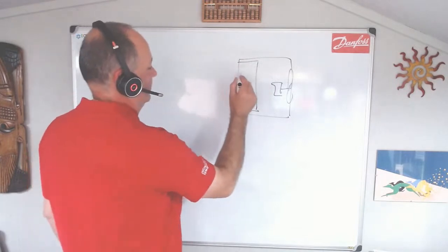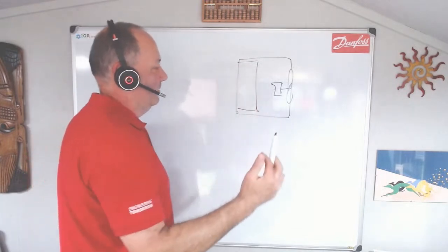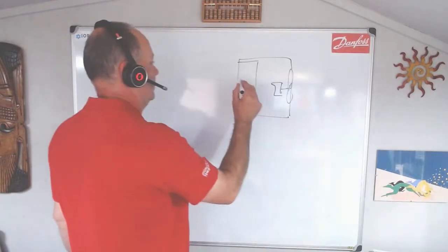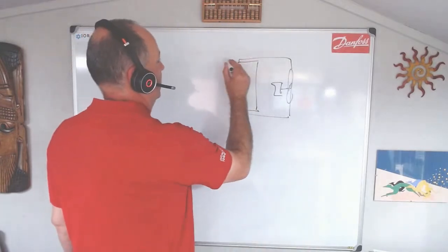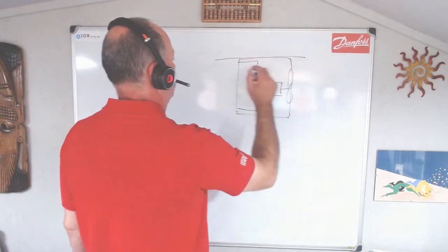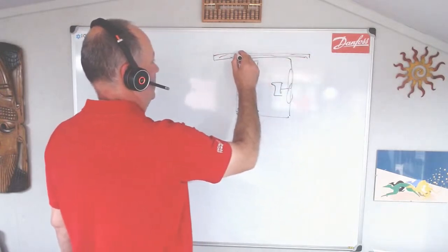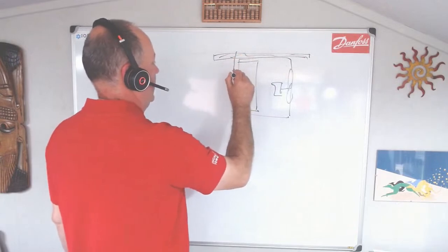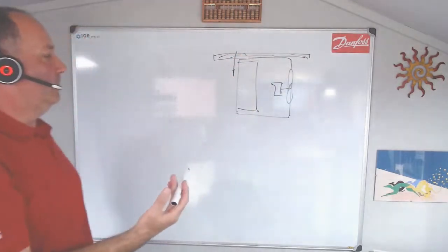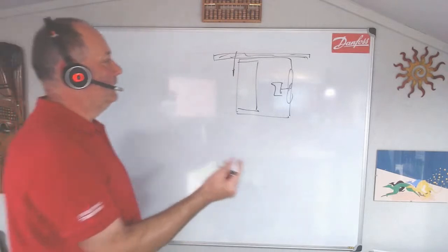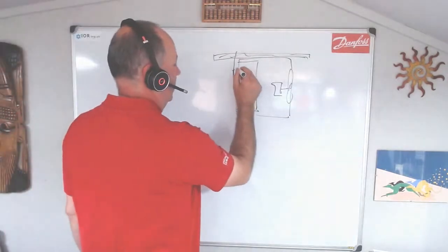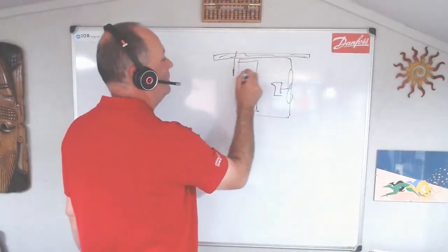Defrost termination sensor, and again, I spend quite a lot of time on site, have done for quite some years. Let's say that's the top of the ceiling. I've seen a defrost termination probe just hanging in midair. Never going to work. It needs to be clipped to the surface of the coil.